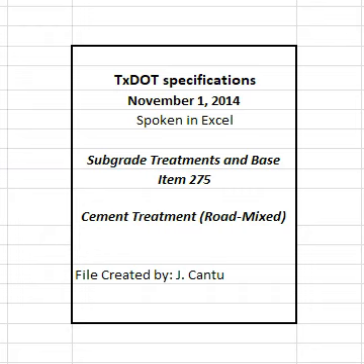2.1 Cement. Furnish hydraulic cement that meets the requirements of DMS 4600, hydraulic cement, and the Department's Hydraulic Cement Quality Monitoring Program, HCQMP. Sources not on the HCQMP will require testing and approval before use.